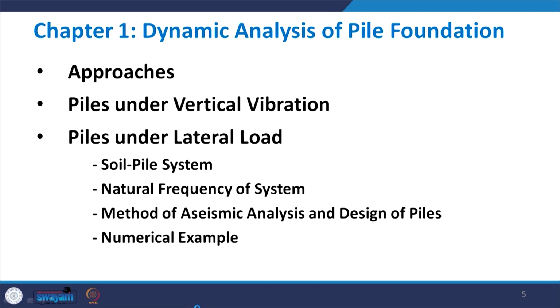Then we are going to talk about piles under vertical vibration, where the load applied is simply vertical. Though this will not represent the real case, this vertical load may be due to other reasons also. It could be due to machinery or some man-made loads. So the load considered is vertical. The third component is the major component of today's and the next lecture, that is piles under lateral load, which will be covered under the soil pile system, natural frequency of the system, and once we have worked out the natural frequency, we are going to talk about the response also. Once the response is over, then the method of seismic analysis and design of piles, and finally some numerical examples.